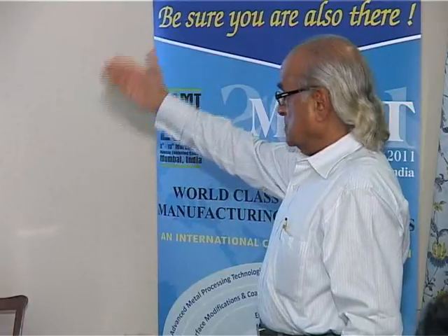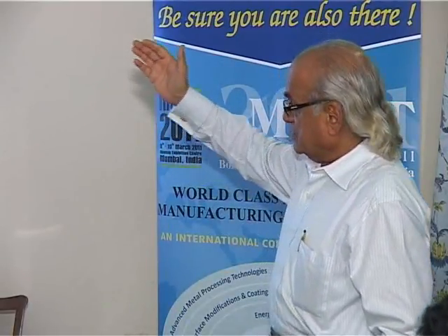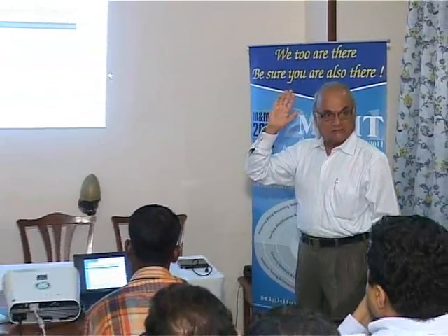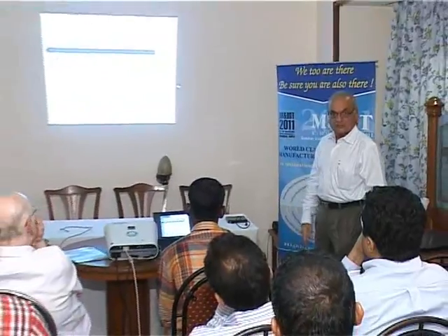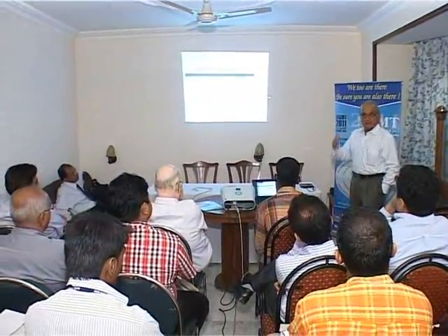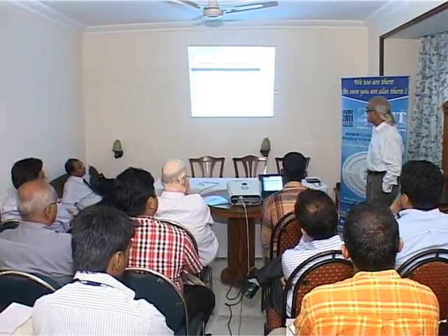And as I said, the items you have to think of: in case the oxygen level goes up due to, say, leakage or infiltration, the system should be capable of giving not only an alarm but also pumping nitrogen into the furnace so that the explosive situation is totally avoided. Safety becomes a very crucial feature in hydrogen filled annealing furnaces. Next.